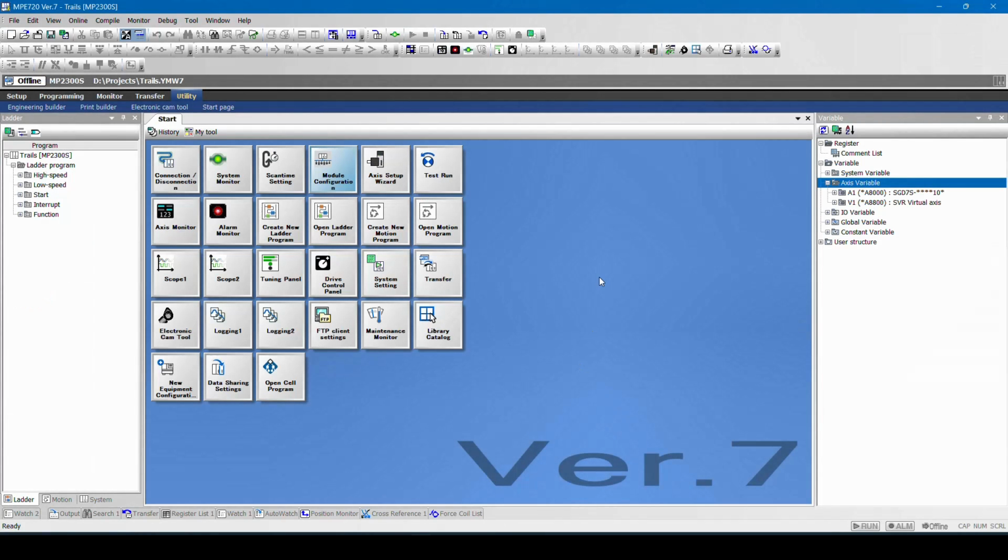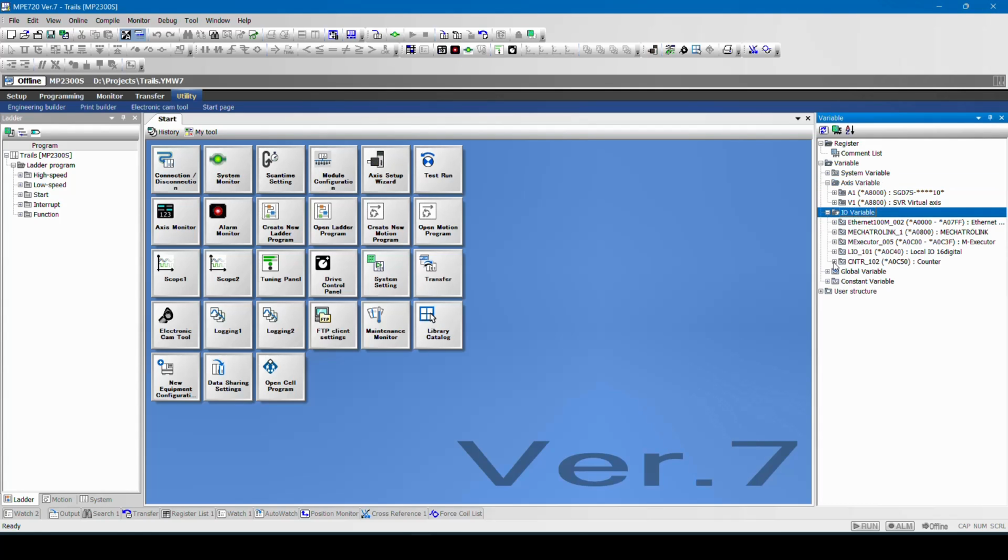So now I'll go here and click the save option. So now the project is also saved, but I have to check whether my IOs are available or not. So I'll click on this, I'll check. These are the two IOs which are available. Local IOs, 16 input output and one counter.